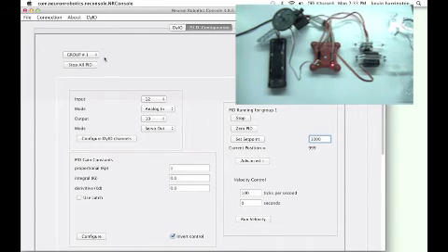It should be noted that the PID controller is running entirely inside the DyIO module. This means that all of the control loops are running real time. What that means is inputs are calculated right on the DyIO controller, and outputs are set directly from commands inside the DyIO.